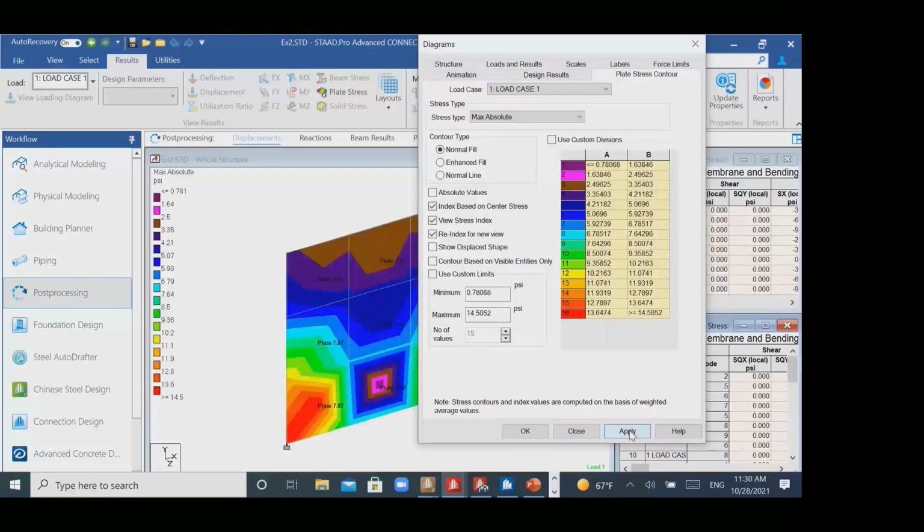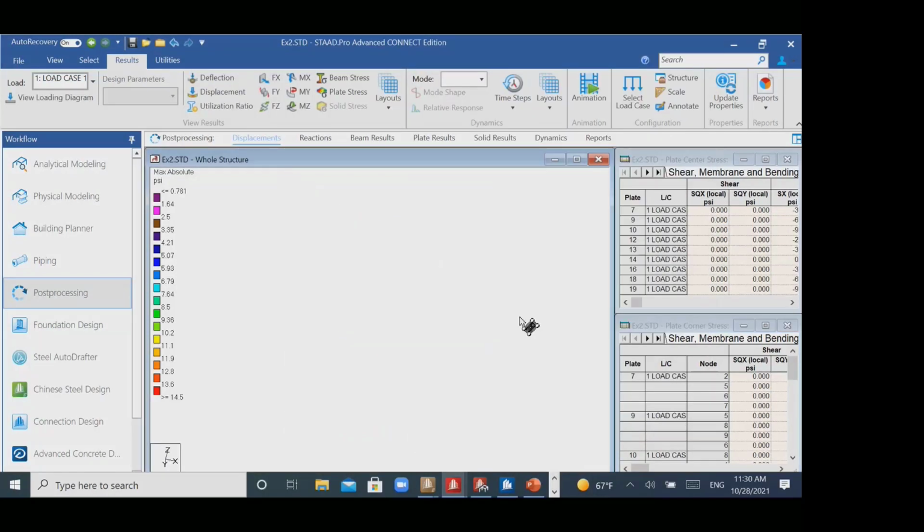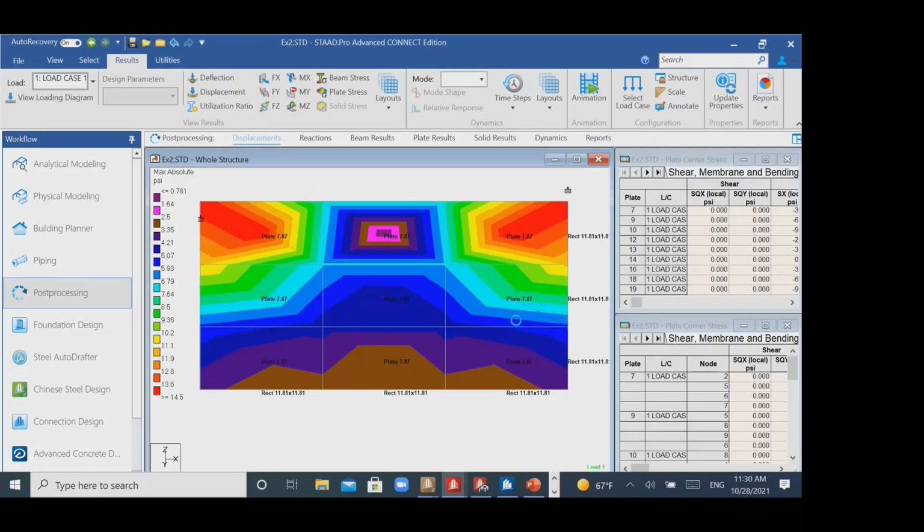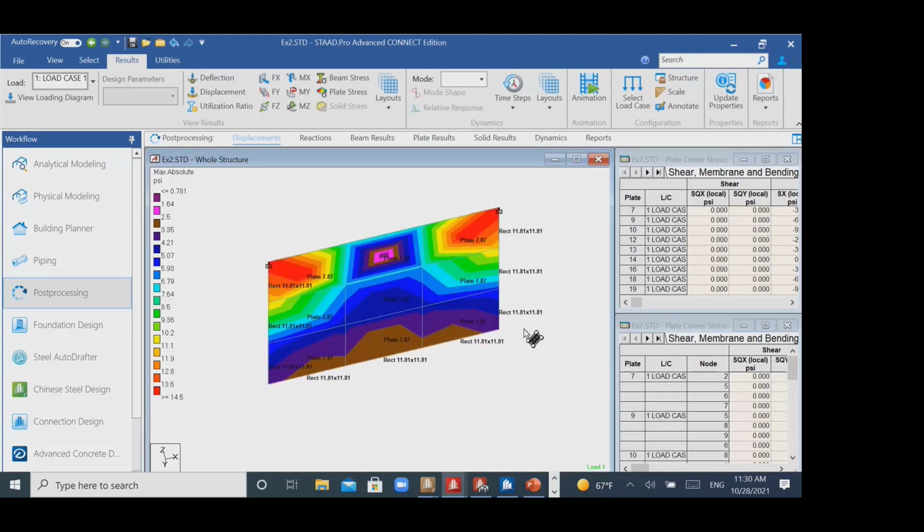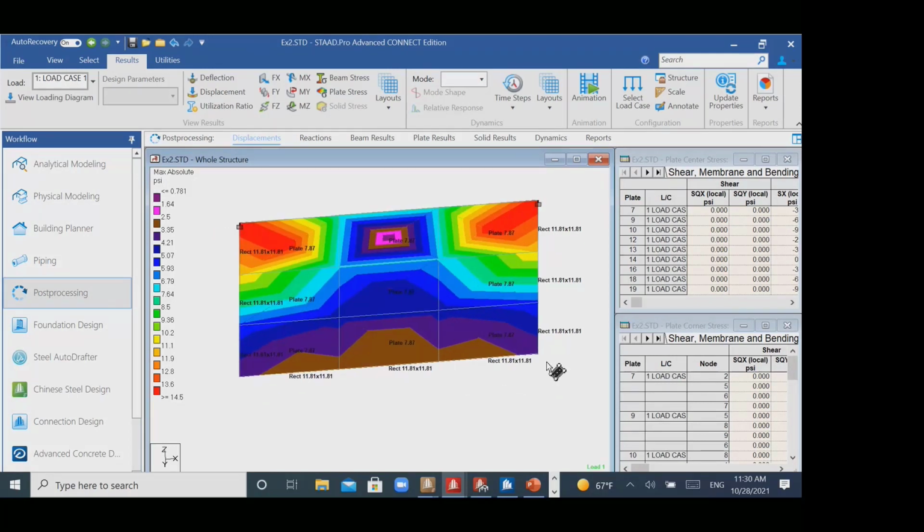Of course, if we have something more plain, we can do the checking also, it's the same, okay? And the interesting part of maximum absolute, usually the maximum absolute represents in color the maximum stress, and you can check with the maximum allowable stress in your material.